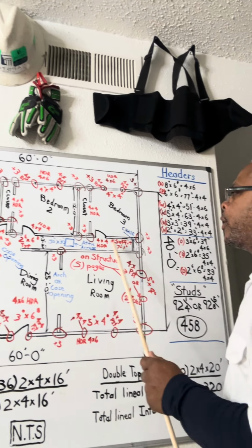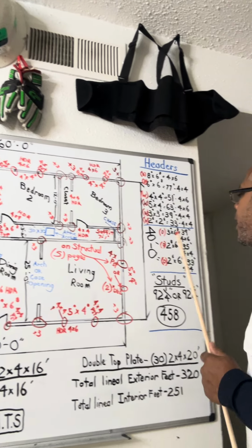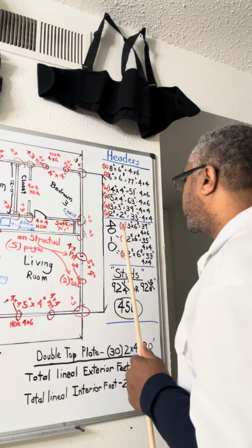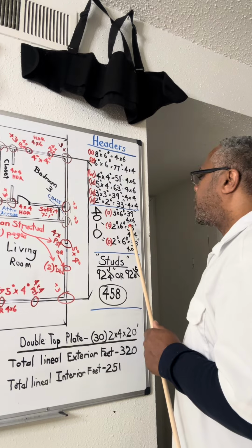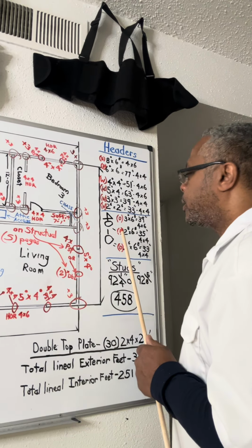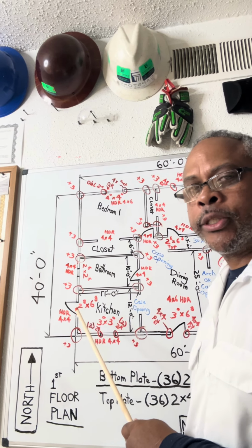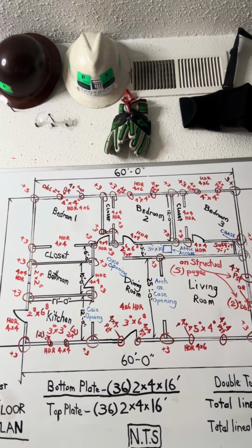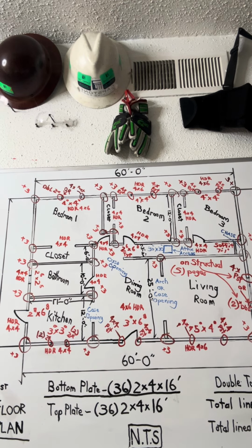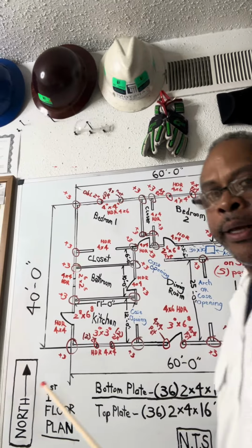Okay, so all our doors, typically, headers are going to be 4x4. So a 4x4 header, 48 inches, okay? So we typically got a 2.8 by 6.8 door. 2.8, that's 32 inches here. Back door doesn't have to be 36 inches like the front door. That header is a 4x4 header, all right? For our front door, we want a 4x6 header because of how engineering is, okay?